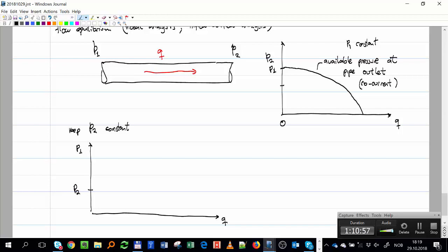Okay, so when I increase the rate, it's increasing, all of you? Yes? Agree on that? Okay, because, why? You have to have a higher pressure, right, upstream the pipe, just to be able to flow that rate, a higher pressure. So that curve will look like that. And this pressure I call the required pressure at the inlet of the pipe.